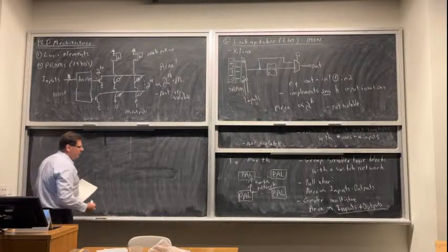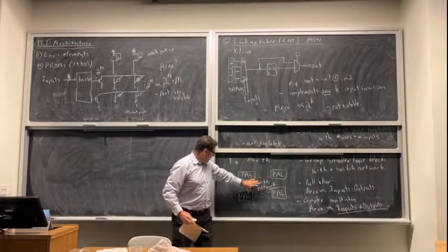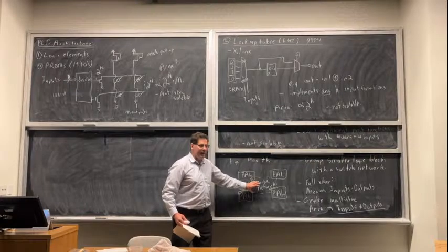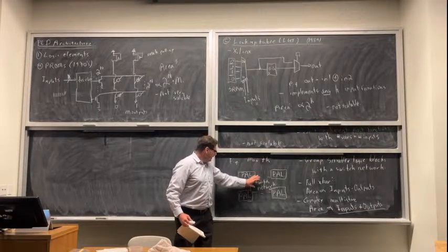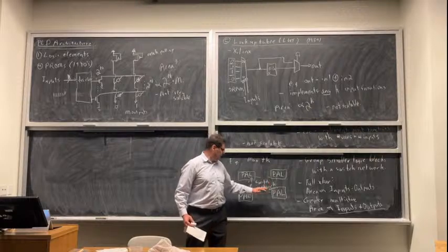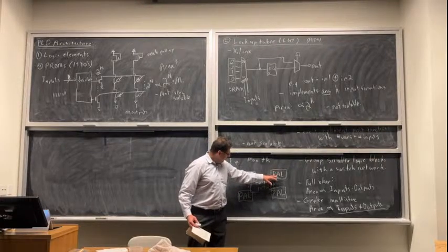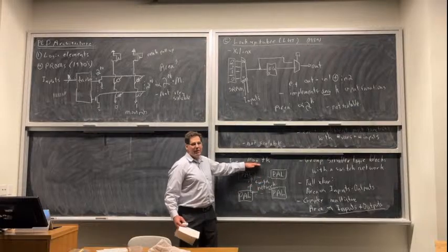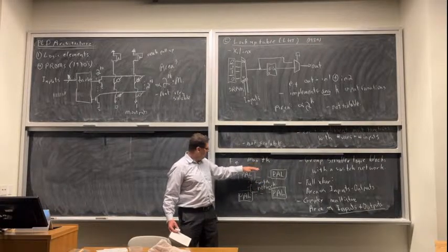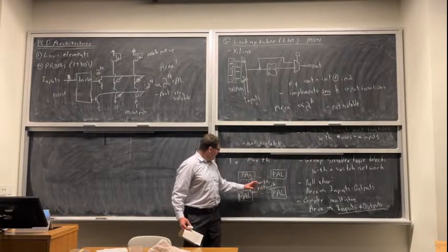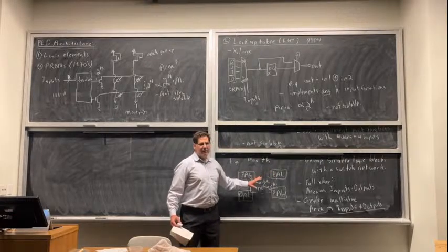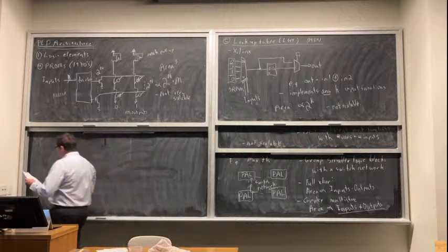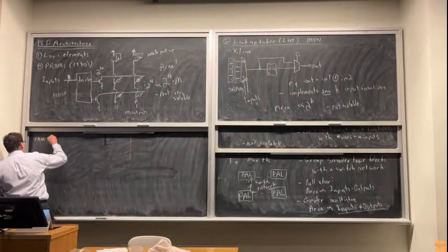So this is basically one level of hierarchy, or maybe 2 levels. I've got logic blocks, and then they have a switch network between them. And this switch network, as long as the number of inputs and outputs aren't too big, so I've got 4 of these blocks, maybe that's okay, I can make a crossbar. And in fact, this chip did just use a crossbar. So it works when you've just got 4 things connected to it. But if you made this into 16 things connected to it, the number of inputs and outputs starts getting unwieldy. So to go to bigger chips, hierarchical FPGAs have to go multi-level.